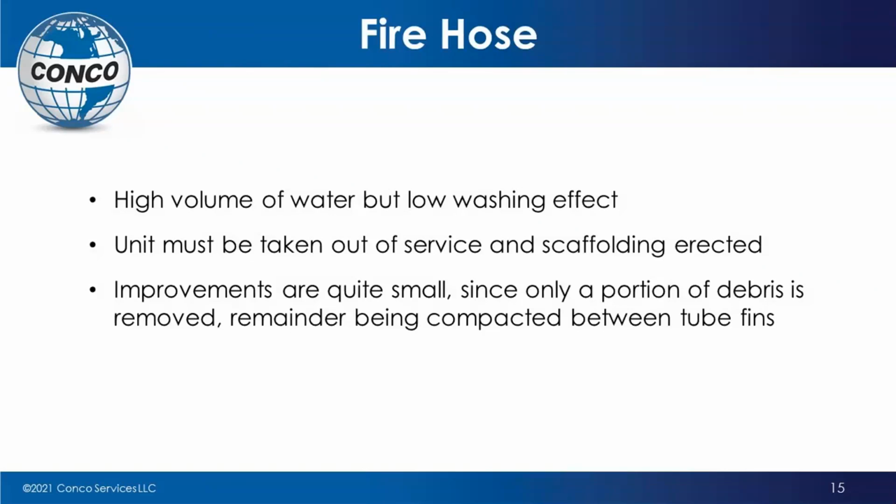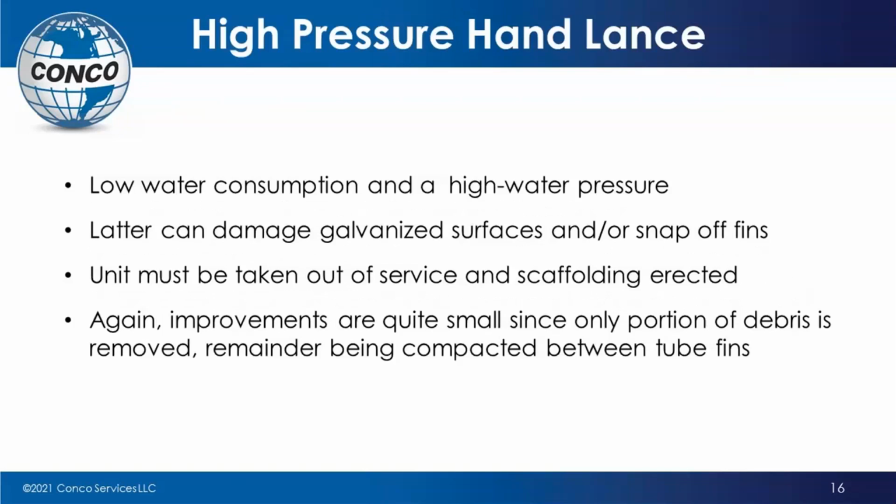But in many instances, you just drive the debris from the top level down into the lower levels of the fins, into the second and the third layer of fins, and you begin to cause more problems because you're compacting that now. So in the end, you get small improvements since only a portion of the debris is removed, and you get a lot of compacting of that debris down into the fins themselves, which could cause bigger problems for you.